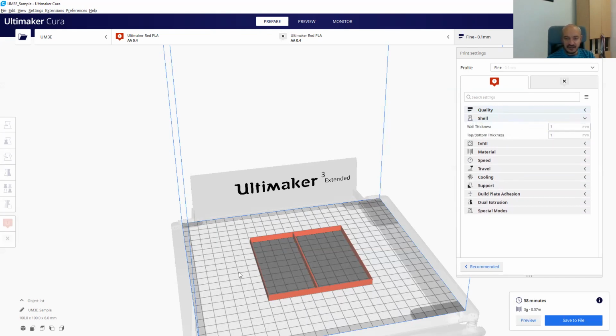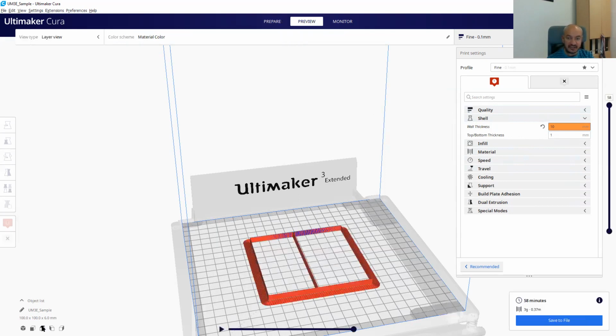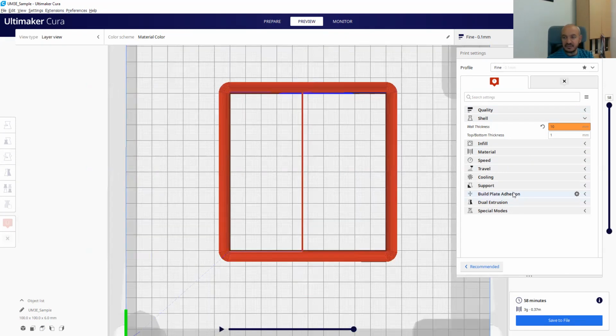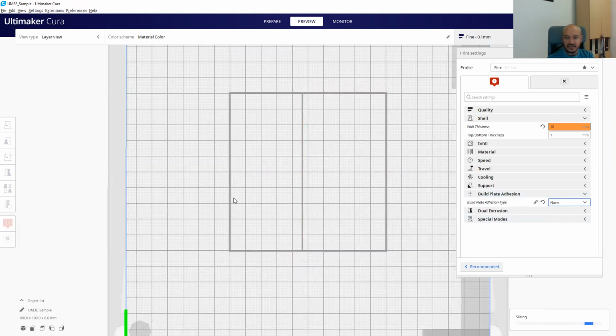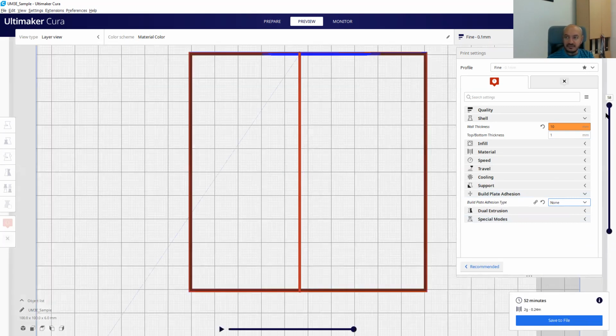Right now, in our case, the shell is not important, but depending on your task, you may play with this one. But even though I increase this one, let's say to 10, there will be no change in the Gcode file or the trajectory. Now let's focus on this, I will disable this iteration. Now, since it's a 2.5D part, as you see, all the layers are the same. Just the first layer is a bit different. Now let's have a look at how this layer is printed.